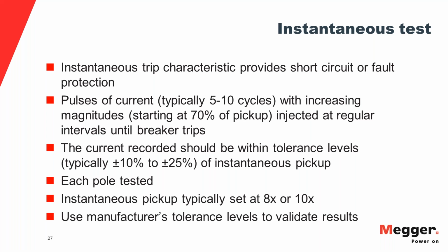Now let's look at the instantaneous test. In the instantaneous test, the instantaneous trip characteristic is provided for short circuit or fault protection. There is no delay here. The breaker is supposed to trip as soon as the current crosses the pickup value.